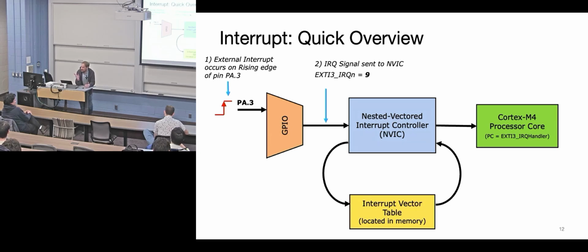That's the interrupt priority, I believe. It might be -3 for the interrupt priority. Looking at your slides, what does my slide say? 0? Nope. So close. 4? 4. Why? What's that 0, 0, 0? The stack pointer. So it just tells you where the stack is. Remember, the hardware doesn't know. Why doesn't the hardware inherently know where the stack is? Why can't we have a default stack pointer?